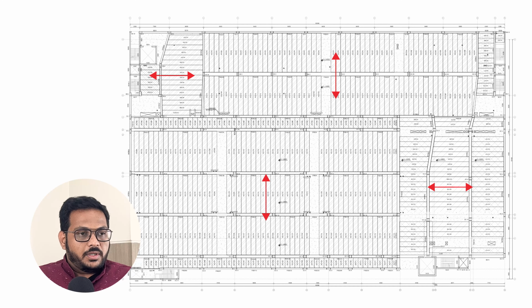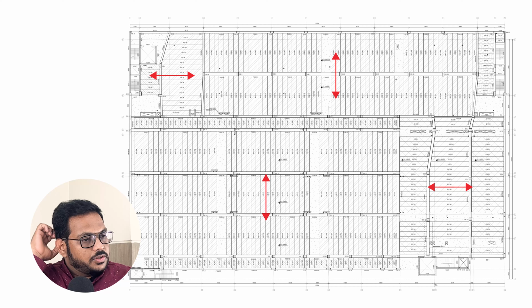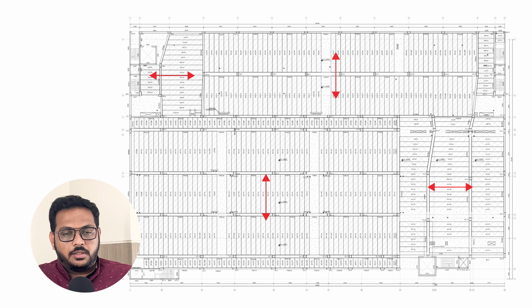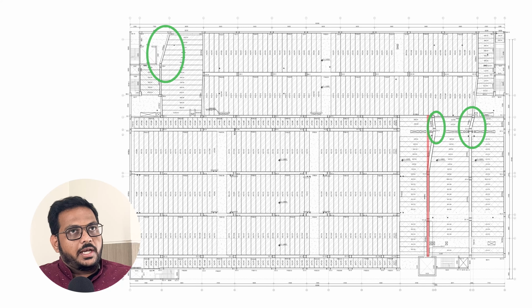But in this condition it was very different because storage was also there in that data center, in the same building. So there were a lot of orientation offsets in the columns itself, and it was so critical that, to lessen the amount of beam reinforcement and the heavier beams, we had to change the orientation.